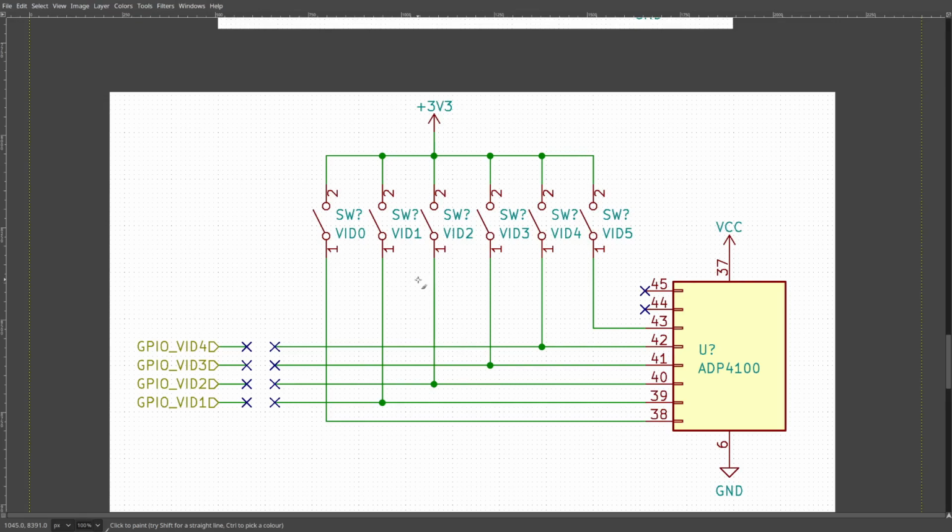There's a risk of basically damaging bits of the GPU core. Now, are those critical bits? It's hard to say. But avoid that if you can, obviously. So in this example, I have vids 0 through 5 controlled. We're just going to connect the last two vids to ground because, I didn't really show this before, but you can get enough range without those last two vids for basically all your overclocking needs. You don't need to be able to go down to 0.8 volts or below that. It just is not practical at all.